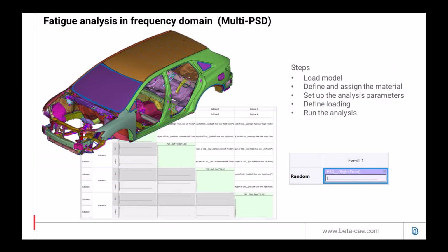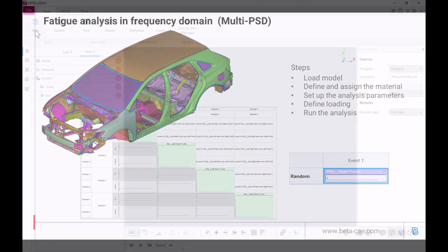Continuing with importing a different model, we are going to study the fatigue life of a few selected subframe and rail components of a vehicle under loading in the Z direction, coming from a certain road pattern. The loading is applied in the 4 spring damper mounts of the vehicle in the Z direction. The input signals act simultaneously and are checked for cross-correlation during the signal processing, thus resulting in both PSD and CSD inputs in terms of displacement. The stress FRFs are given as 4 different subcases under the uniaxial loading at each spring damper mount.